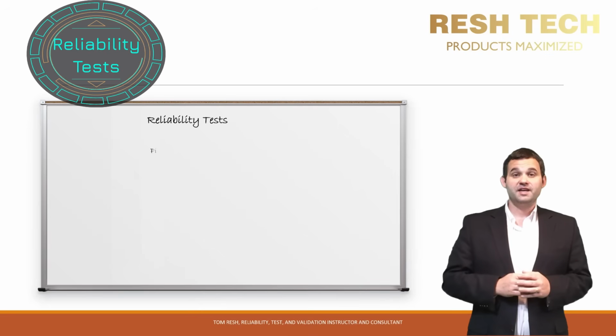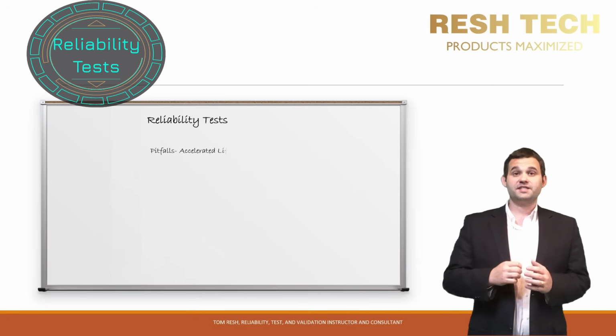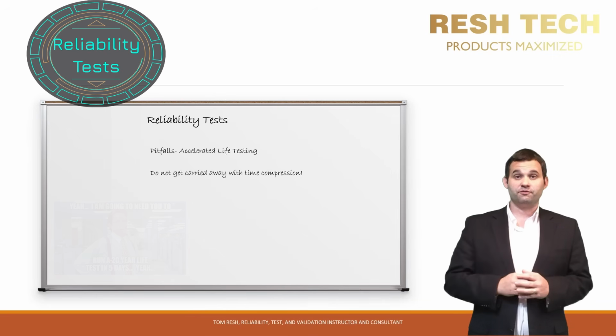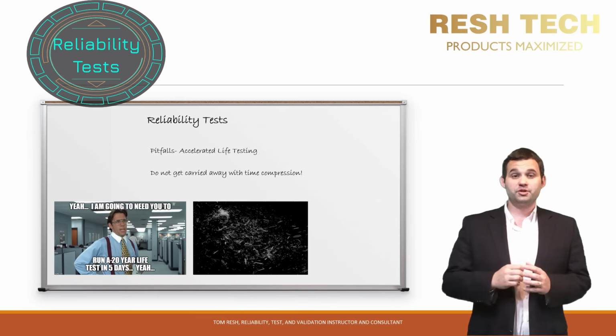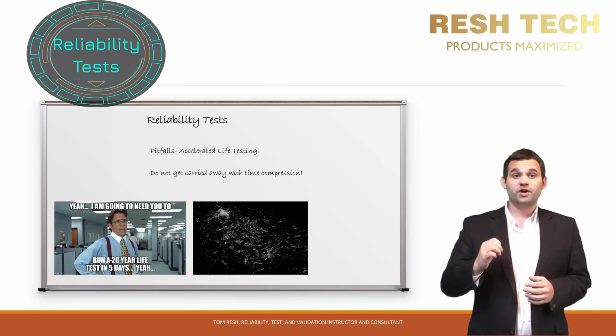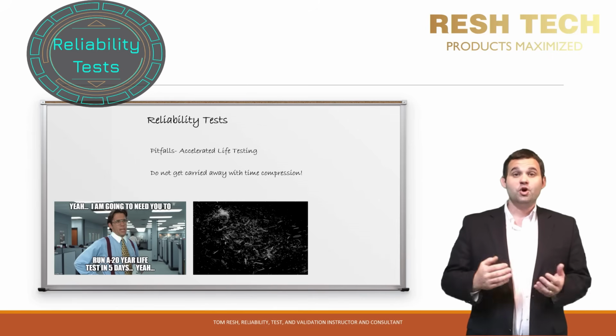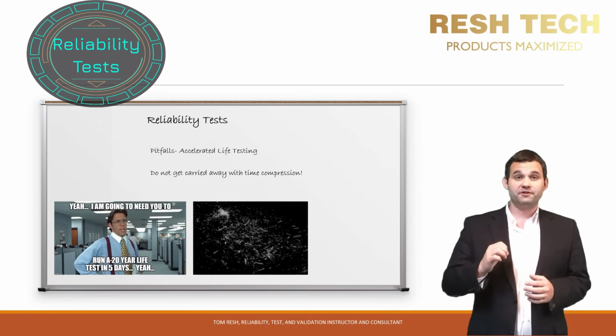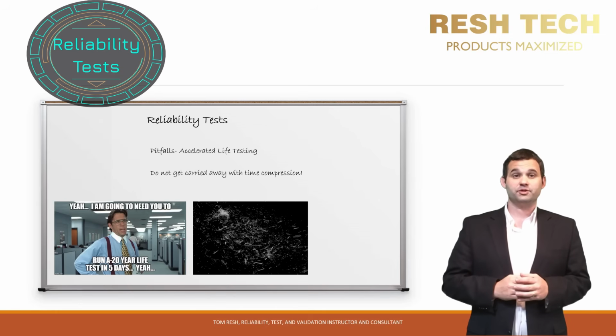Again, keep in mind that there's a limit to how much you can accelerate tests by increasing stress levels. You need to understand the design margin and safety margin for your system so that you do not produce unrealistic failure modes or create an unintended safety event when your system is destroyed by severely high and abusive stress levels.